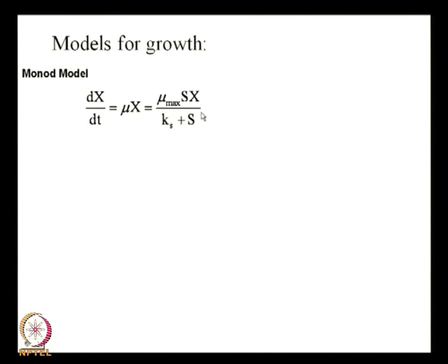For all other kinds of reactors, dx/dt is not just the reaction rate, but there are input and output terms that have to be added in. So do not ever write dx/dt equals reaction rate unless it's a batch reactor. I tell students, but I still keep seeing these mistakes on the answer sheets. It's a very straightforward thing, but you still need to remember it.